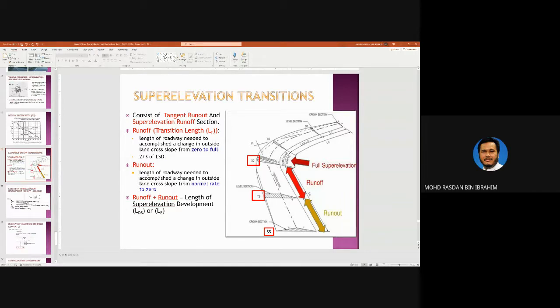So in the spiral part, when they say crown section, it means that this is normal, 2.5, 2.5. I'll just use negative, negative 2.5 because it is going down. Okay, negative 2.5 going down here. Here it is 0. So this is negative 2.5. This is also negative 2.5. It does not move on the right hand side. This side is starting to move.